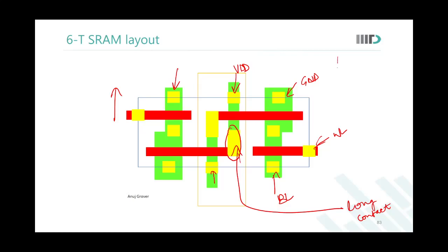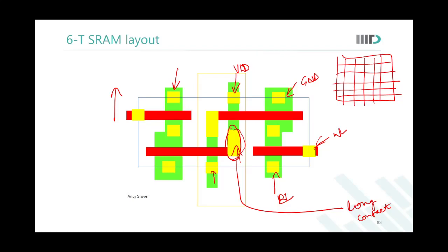So what Raghav over here is telling us is that this memory cell would always be there in the form of an array. It is not that I want to make one set of contacts in some region and the remaining area is completely out of my control. When we talk of an SRAM cell, I know that in this whole 1000 micron square of area, this kind of pattern would appear over and over again.